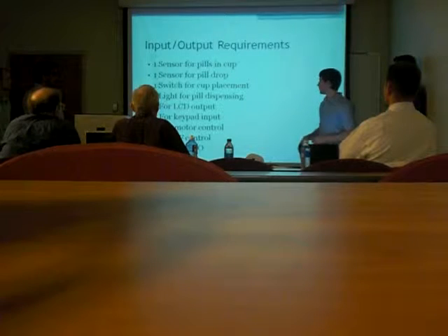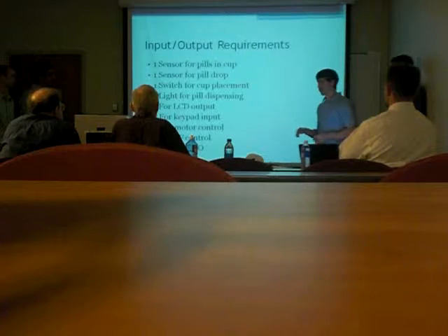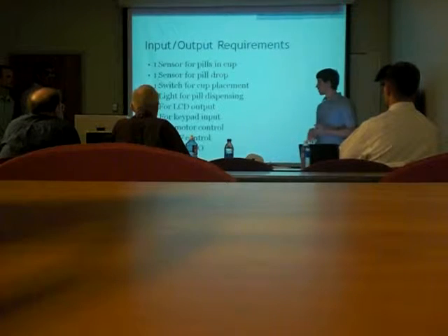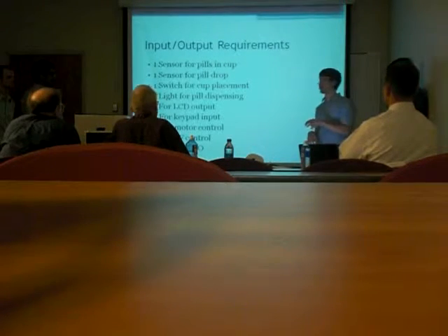One for the LCD output, once again the 7 for the keypad input, and 8 for motor control, which consisted of, as Jacob mentioned earlier, 4 to send the signals to the motors, and another 4 for the switches that would be controlling the stopping and starting.